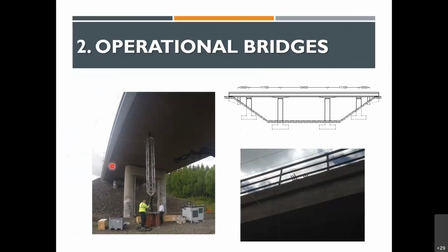And what was being done was, while this entire bridge was live and trains were passing over it, we were shaking this bridge up and down as a chirp. So first in increasing frequencies up to 150 hertz, and then in decreasing frequencies, and many, many rounds of it while the train passes over. So it's a very exciting experiment overall, as you can think. And then we had accelerometers and harvesters side by side to see, okay, is it making sense?